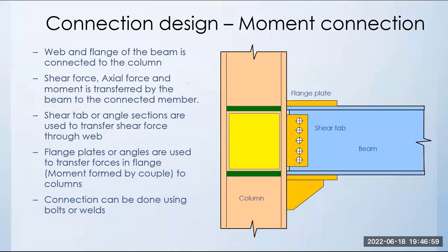The weld connection only takes care of shear force, right? No, it can take anything. You have to proportion it accordingly, whether you are welding the flange or the web. Depending upon its position, it will take either shear force or moment. You can provide it based on its location. It will decide the transfer of forces.